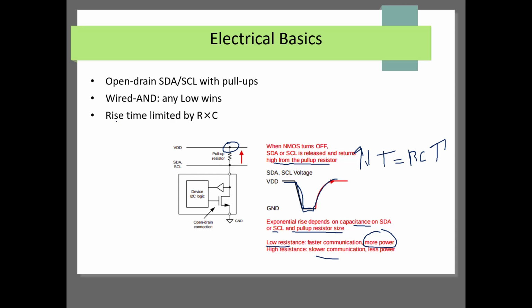See, rise time is limited by the time constant, sorry, R and C, resistance and capacitance. Now, wired-AND means any low wins.